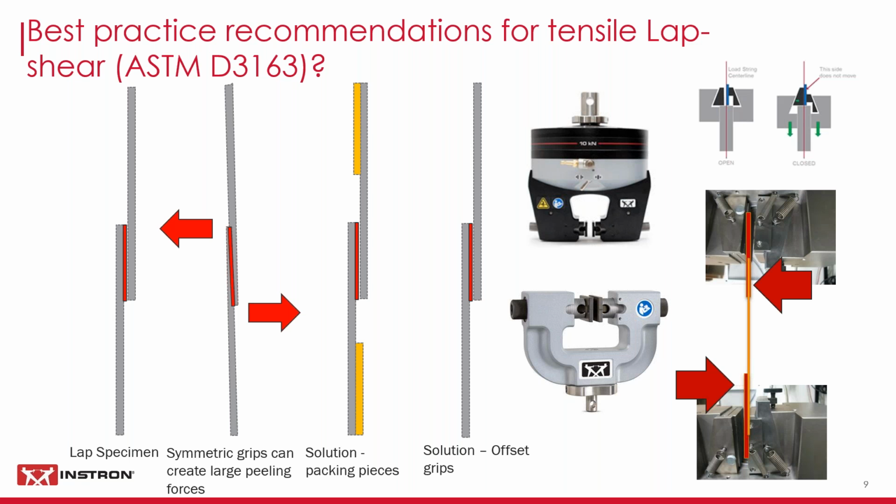And we can also supply special wedge grip inserts for our 100 and 250 kilonewton precision manual wedge grips, which will also allow offsetting of the wedge grip. So that allows us to test very high force lap shear joints using those grips.